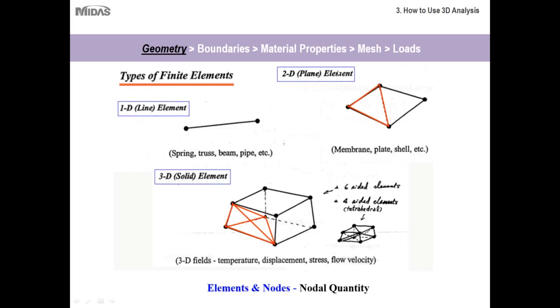Next, there are 2D or planar elements. These are the next level in complexity. As you can see, it's a series of nodes and lines that are connected, but within this frame there'll be what's called a surface. And upon this surface, you can model strains, displacements, and moments. So in addition to these edges and nodes, the surface can also be analyzed. This is typically used for plate or retaining walls, as well as excavation types, and other flat structures that you can imagine.